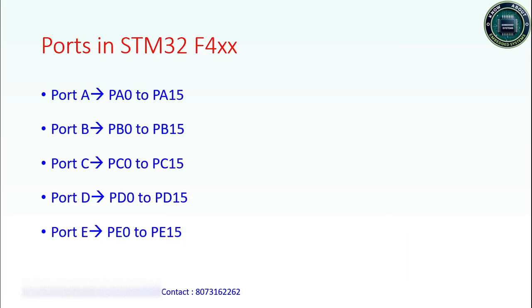Before starting the video, you should also know one more important thing: how many ports are available in your microcontroller, that is, the STM32 microcontroller. In the STM32 F4 microcontroller, we have 5 ports, including H, so actually 6 ports, as you're seeing on the screen currently.